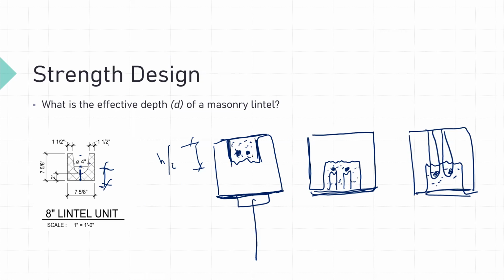And so usually we're not going to see this grouted core beneath it, depending on where that window or door frame is located. But again, if we're using a split face or burnished unit, typically the lowest we'll be able to get our reinforcement is about that unit height divided by 2. If we have a closed bottom or U-shaped unit, typically we can get the centroid of the rebar 3 inches from the bottom of our unit, based on the manufacturers that I worked with and got their mold drawings for.